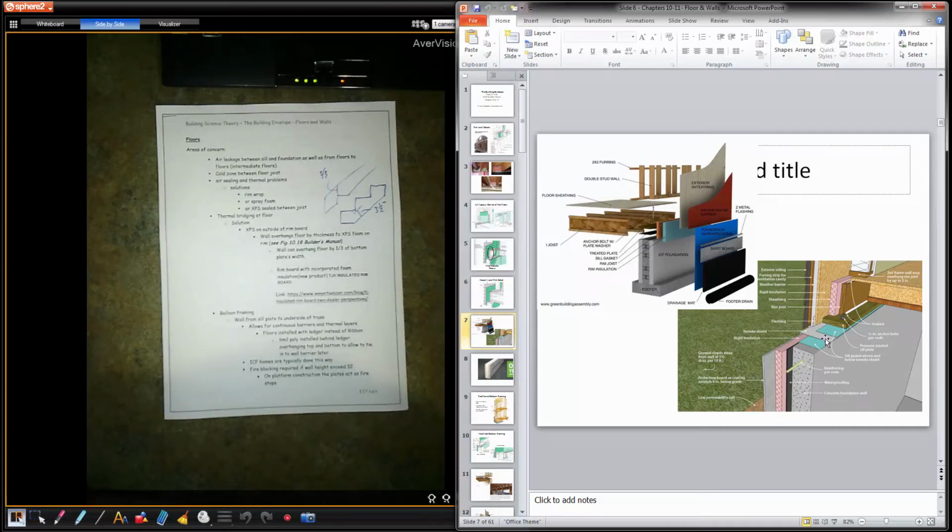So here they're showing 2 sill gaskets. A sill gasket and a termite shield and another sill gasket. Pressure treated sill plate, foam board, wall is shifted out. 2x6 frame wall may overhang rim joist by up to 2 inches. Okay, so 2/3 rule. And then foam on the outside, we got damp proofing, protection board, probably cement board.